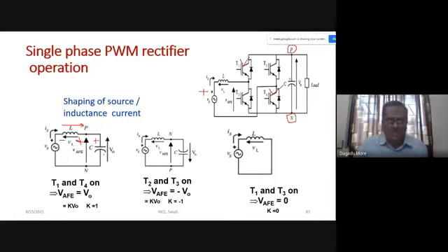capacitor voltage. So I think it will be clear that when T1 and T4 are turned on in the positive half cycle of AC voltage, our source current has a tendency to decrease, and supply voltage plus inductor voltage will be equal to the capacitor voltage. That is our circuit equation. Now let us consider our other two switches are on. So let us go for